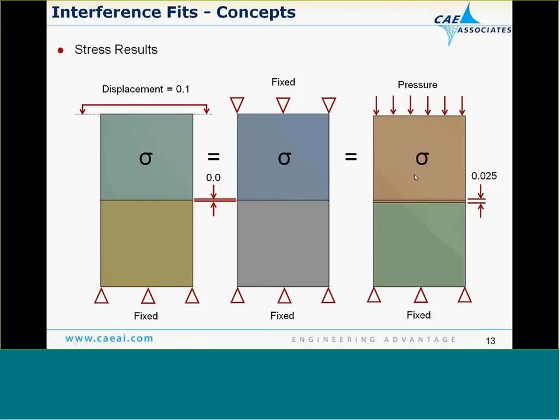But if you're looking at displacement, obviously that's going to be a different answer between the two, so maybe you need to minimize penetration there. But if we're looking at just stress, this case is not going to be sensitive at all to penetration, whereas these two will be directly sensitive to the residual penetration, because that's the only mechanism to get the load in the model in this case, right? We're just holding it fixed, and it goes from that 0.1 to 0. That's going to induce all the load in here. So you have to decide when it's going to be important for you.